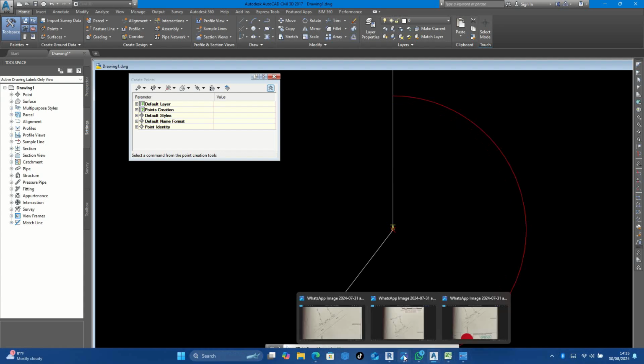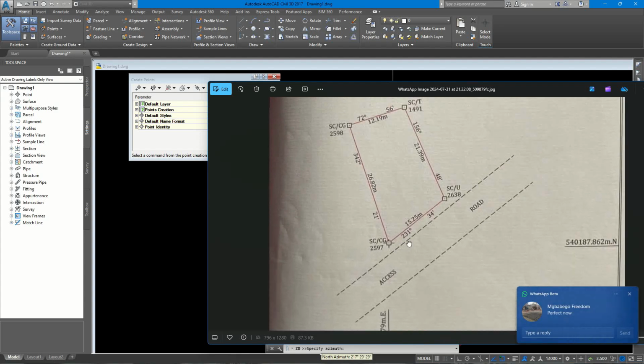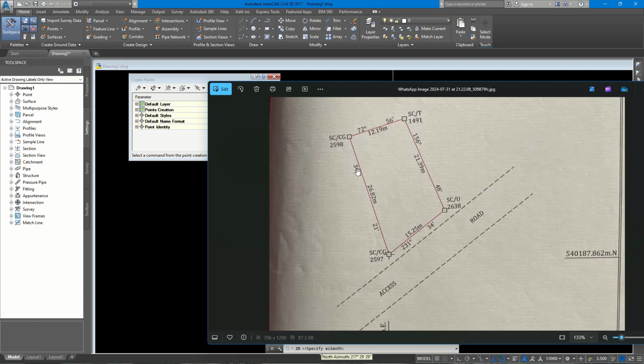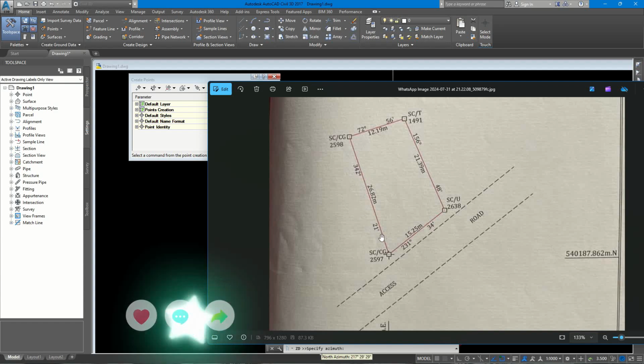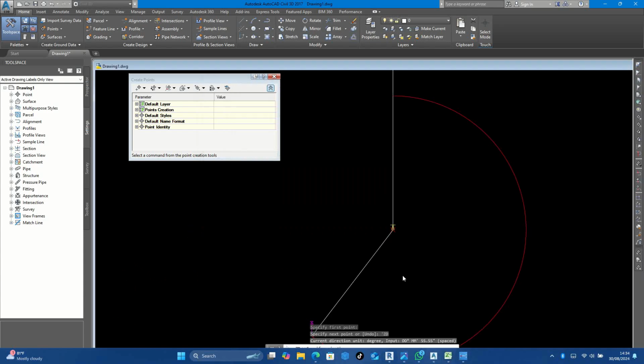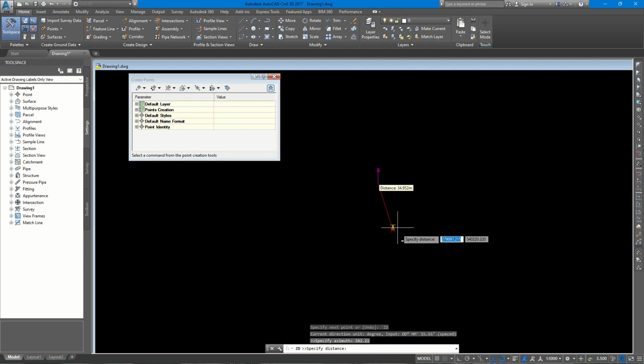surveyor sheet, and this is his takeoff point, and the first azimuth direction is showing 342 degrees 21 minutes. So 342, I will take note of that. Enter 342.21, and it's recorded. So you go back, you see you have the line tracking to that direction.